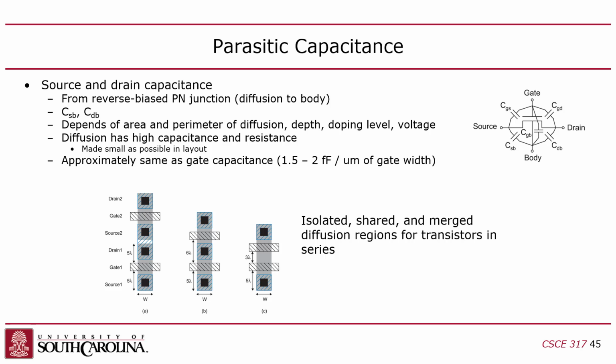Or you can take a shortcut where, instead of having a wire connected to the source and drain of these two, you could just have them overlapping with just one contact. That's more efficient. Or more efficient yet, you can literally create two parallel transistors just by having two gates over one diffusion area.